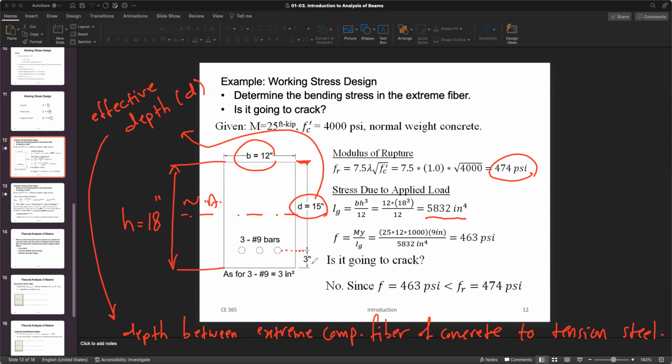And this 3 also is called a lot of times CC or just lowercase c. In concrete, it's not quite there, but I'm going to give you a name here, a little bit different, because we have more to add to this concept. We're going to learn about it more, but it is called concrete cover, all right? So this is not exactly this 3. Concrete cover would be whatever is left after the steel. For example, for this case, concrete cover really would be this much.